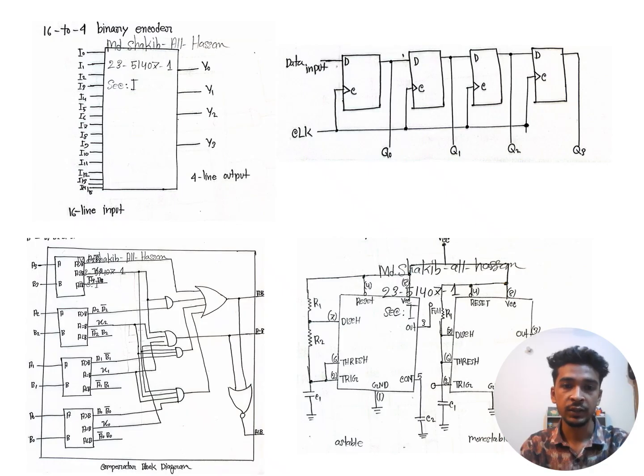Then we use a 4-bit comparator, because the comparator compares the car count. If the car count equals the maximum value, then it is full and it triggers the full signal. If car space is available, then it triggers space available.